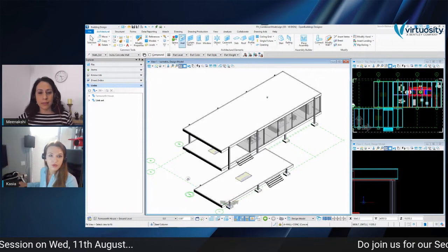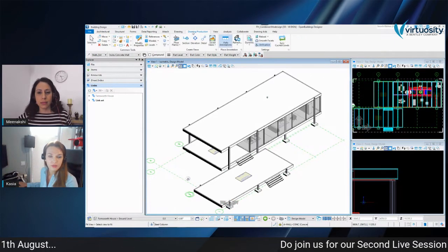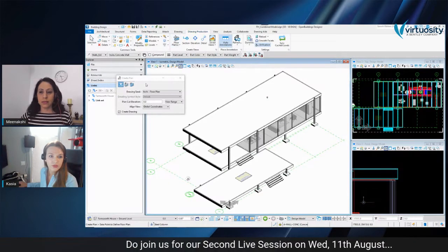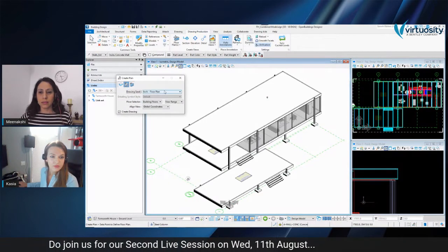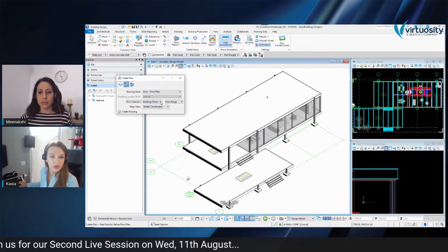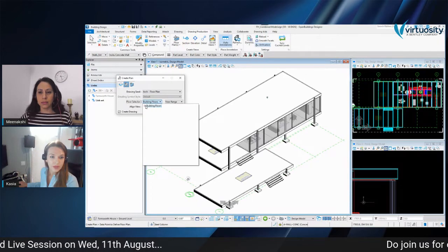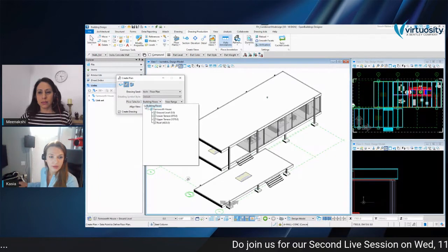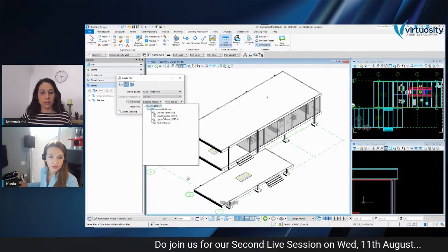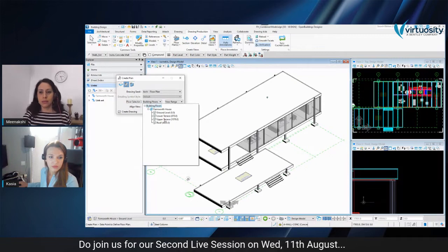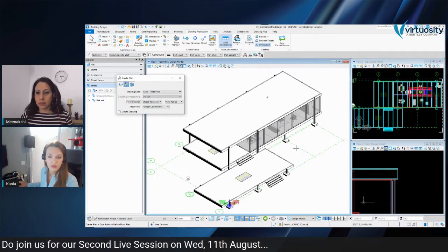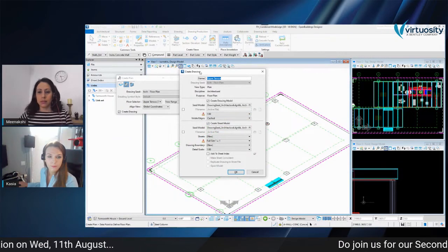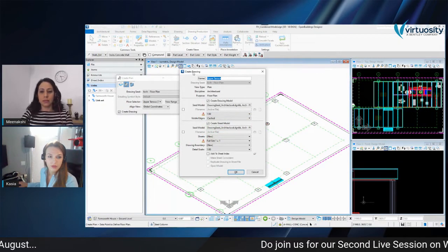Let me go to the drawing production tab now, just to show how it works in general. So we have different types of drawing creation, but now I'm just going to click any type. So in this drawing created by floor, I would just select one of the floors, and if I click anywhere in the view, the drawing will be prepared for creation.